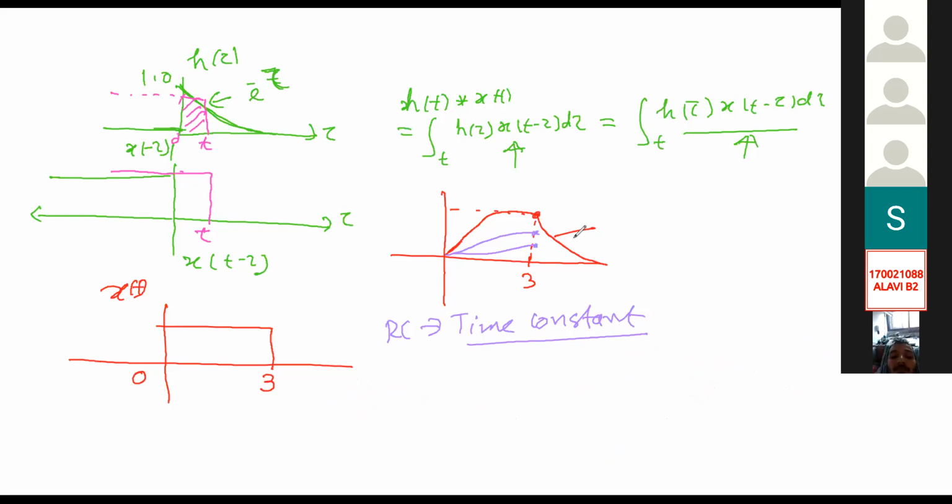Yes, sir. Many students are playing with what we call an oscilloscope. They are simply turning the knob, and when a signal appears, they are very happy, but they do not know how the signal is appearing. So your RC value is one of the important factors of your input side and your probe side, to effectively use a probe to measure a signal with an oscilloscope. If your RC is very long and your pulse is very short, then before your system gets charged, your pulse can disappear. So you will see nothing.